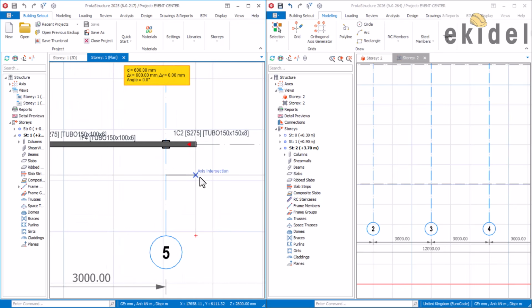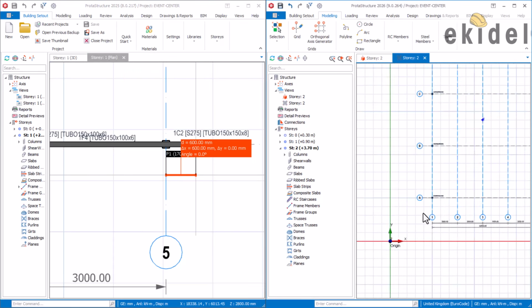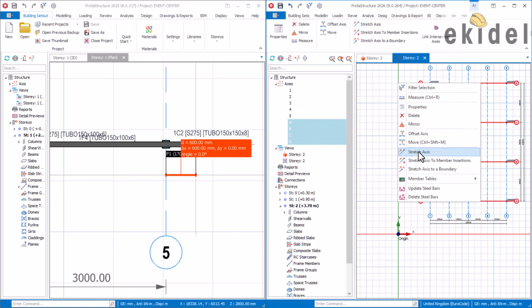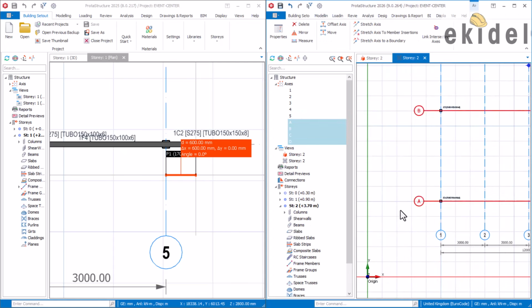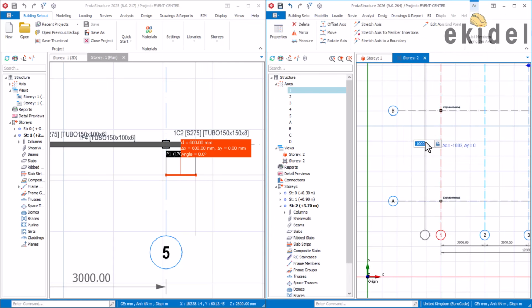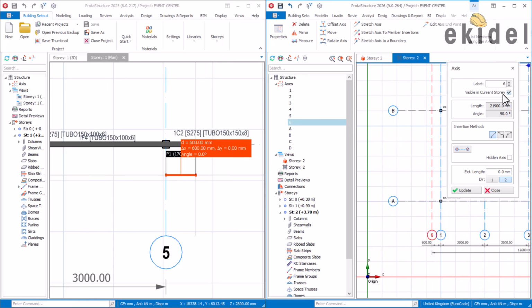Also here 600. So we are going to offset this before I insert that, because that goes above. So we are going to stretch this forward first, because I believe that is going to meet up or clash with something else. So do this first, then click here, right click here, offset, then function F2 key, type -600 and then press enter. Then double click on this, and that opens up. If you want to offset, make sure you press function F2 key before you type your value, then click here hidden, that's fine, and then come here.